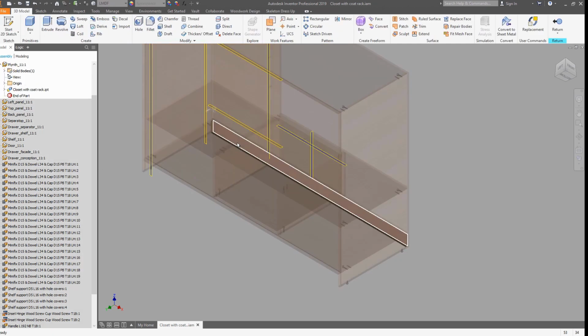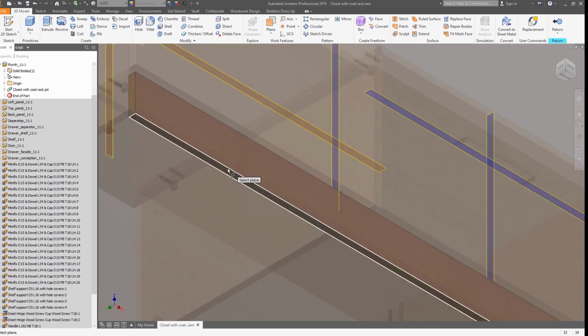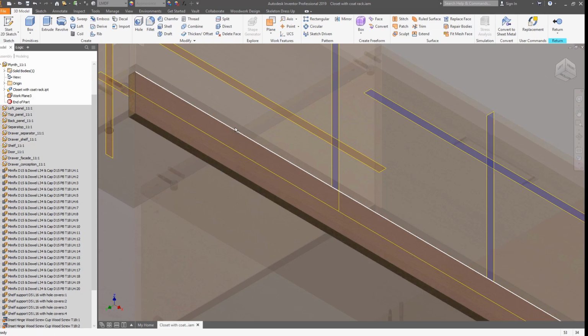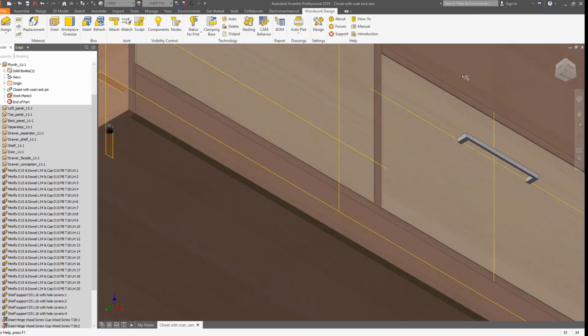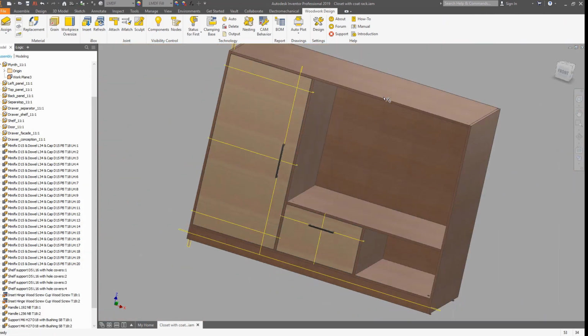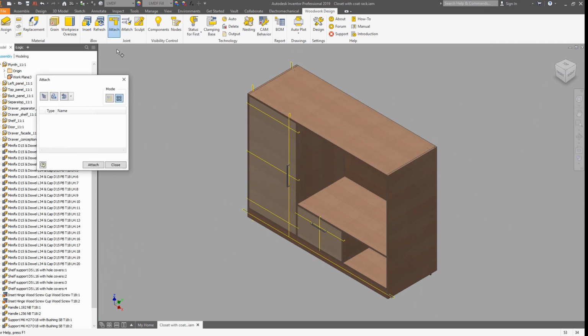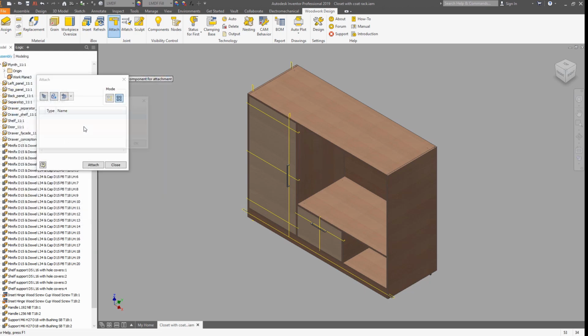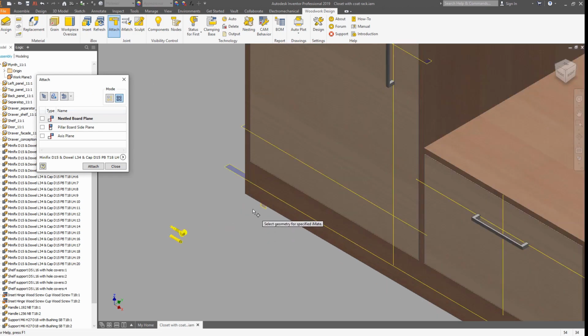Now it's time to fix the plinth in place. Again, the work plane in the middle. Go back to the assembly level. Browse through the structure of the library. Pick fixed join, minifix. Choose a configuration, and that's it. So now we need to just pick the appropriate geometry items, as we already did in the previous steps.